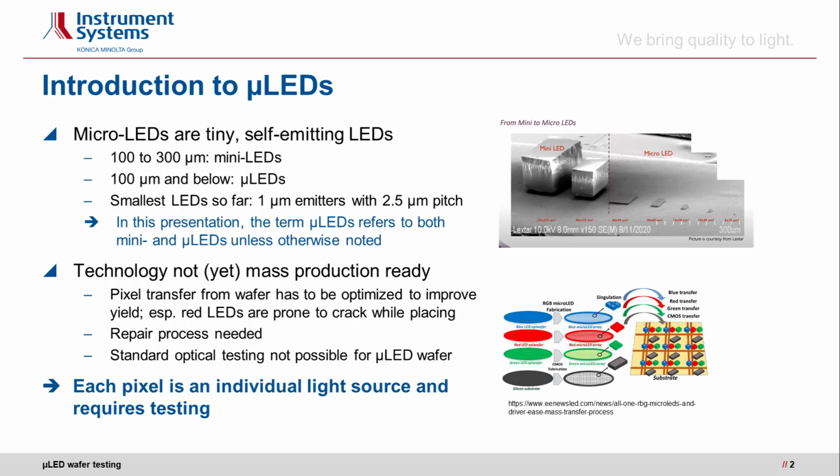Let me emphasize that this technology is not really mass production ready yet. There are several steps which need to be optimized, especially the pixel transfer needs to have better yield in most factories. And we also know that red LEDs are prone to crack while placing them. There will be repair processes needed in case that in the final product we have defect LEDs.